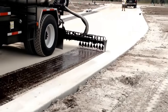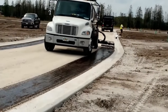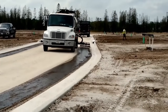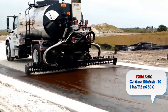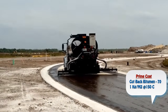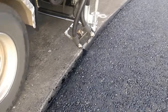The prime coat is the binding layer between bituminous and non-bituminous surfaces, such as Wetmix macadam. The cutback bitumen 70 is used as a prime coat. The material shall be heated to around 150 to 160 degrees temperature, and well blended for 2 to 3 hours, and uniformly sprayed at around 1 kg per square meter over the dry and clean Wetmix surface with the help of a mechanical sprayer. Normally, it shall be allowed not less than 24 hours to penetrate in Wetmix before laying of asphalt work.